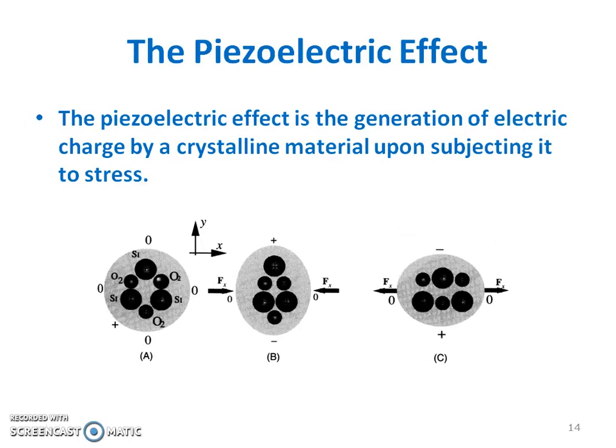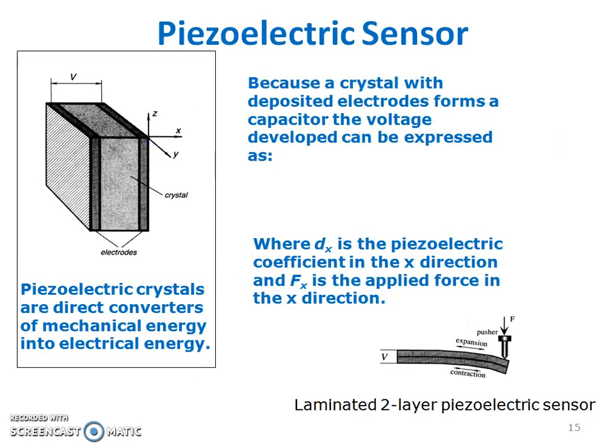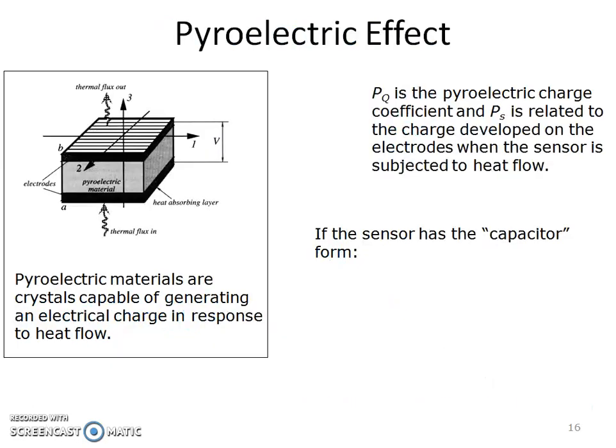The piezoelectric effect is a very famous application in many sensors, and when a stress is applied on a crystalline material, then electric charge is produced. In the piezoelectric sensor, the piezoelectric coefficient in the x direction and the force in the x direction can be equivalent to the stress applied.